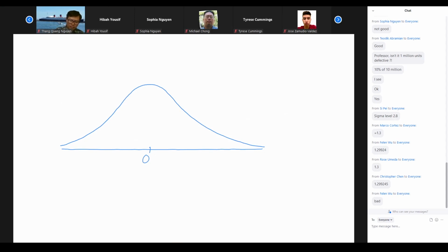The standard normal distribution has the mean at 0, and then we cut the right tail so that the right tail is our probability of defects, which is 0.09693 in our case, or 9.7% defective, right? And of course, on the left-hand side, the P of G, the probability of being good, is 0.90307, right? Okay, so we cut the right tail so that the right tail equals the probability of being defective.